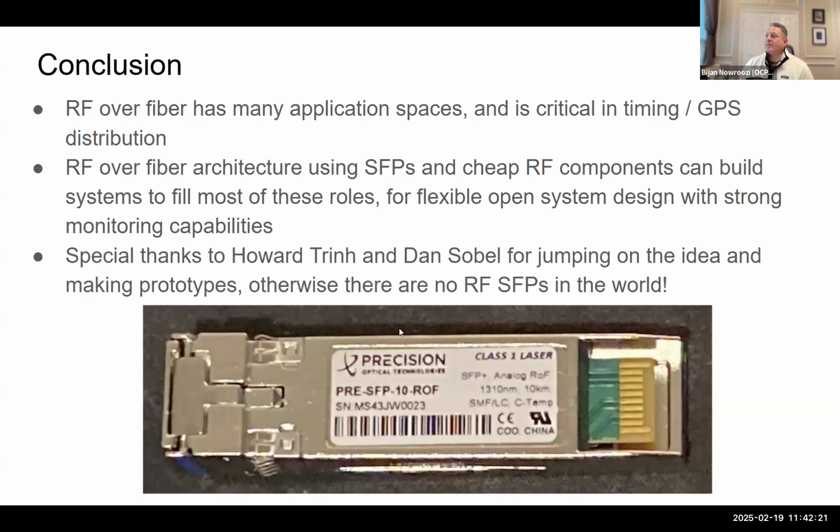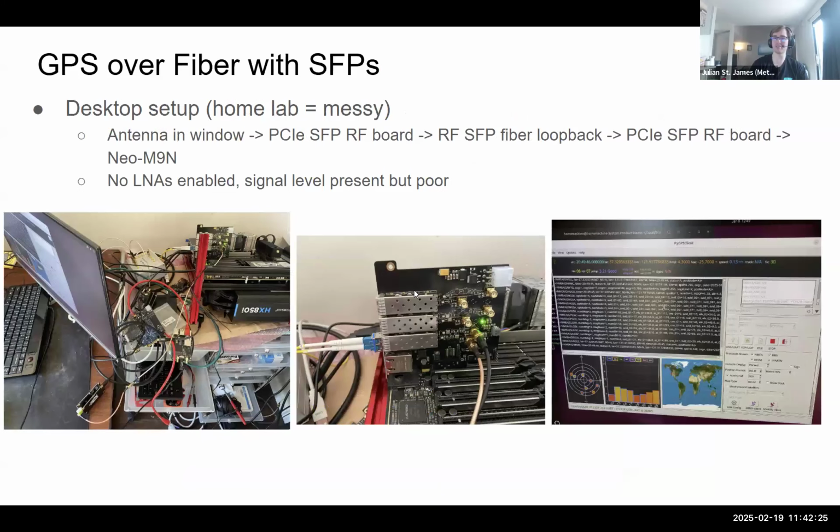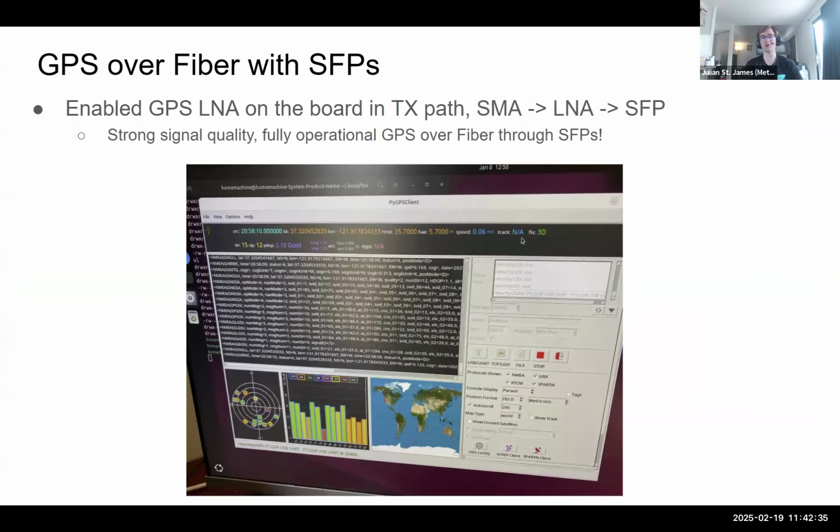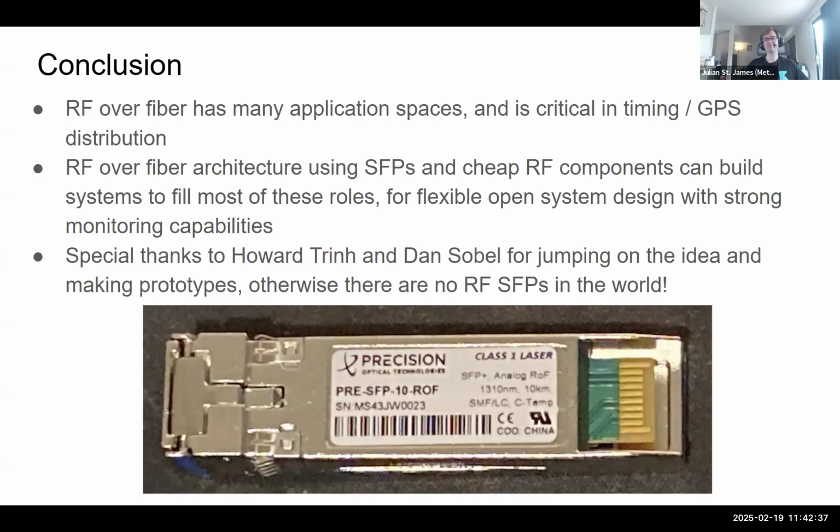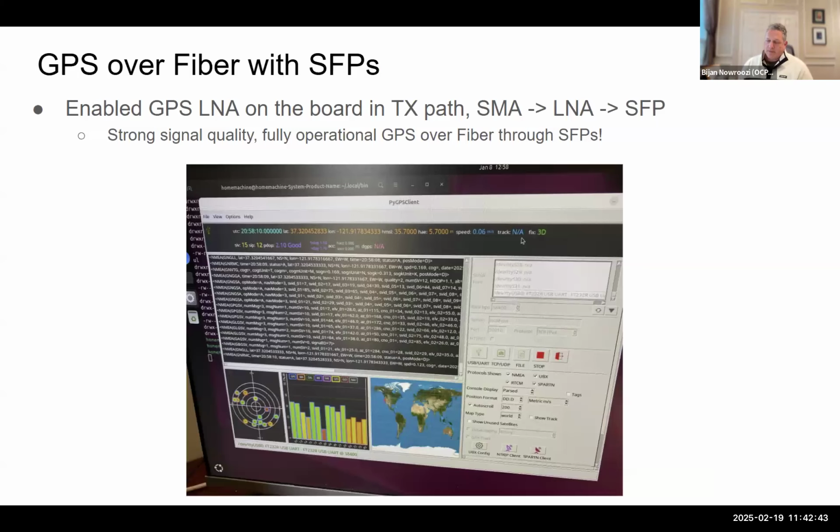Thank you. And the electronics is pretty simple. The board itself is all top layer routing, just RF. So the host board, whatever you design, once you have that SFP, is pretty straightforward, so the cost shouldn't be too high either. And you said you put some filtering after the receiver, right?